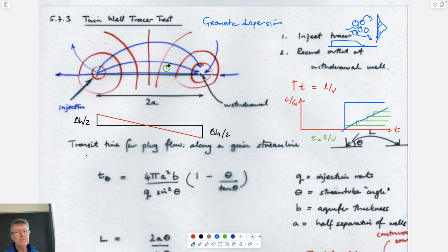And so the mere fact that it's flowing down different stream tubes, and of course the stream tube that goes out here to minus infinity and then comes back from plus infinity is going to be infinitely long into the future. And so the mere fact that you see dispersion in it relates in no way to the mechanical dispersion of your aquifer, it's merely set up by this particular flow geometry that's there. And so if it's a function of this flow geometry, it's not telling you anything about this process, which is what you want to know.